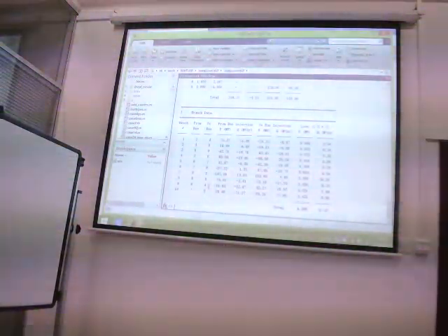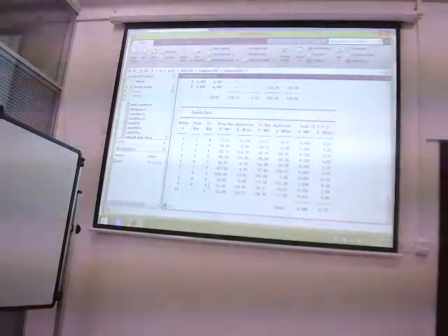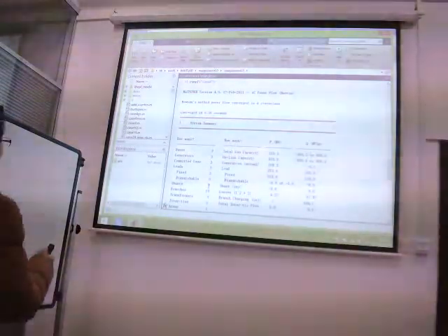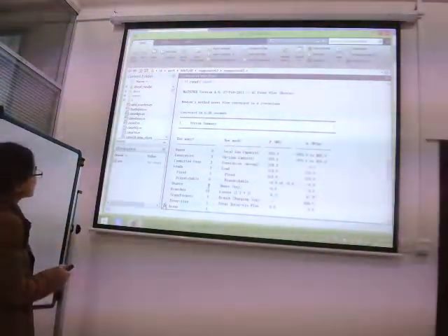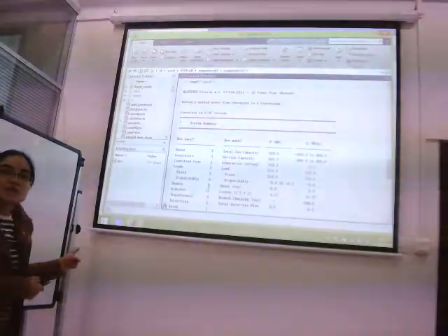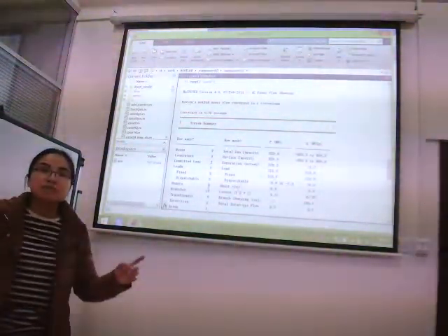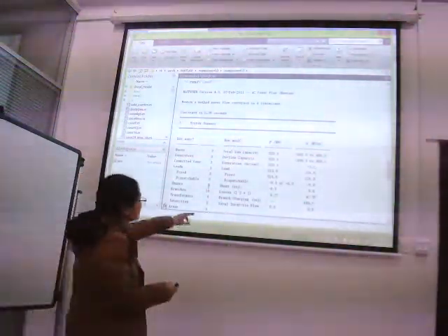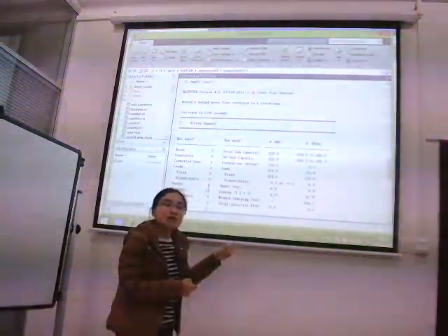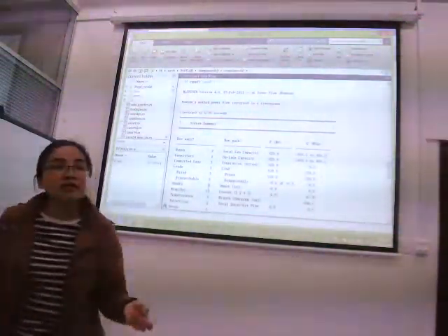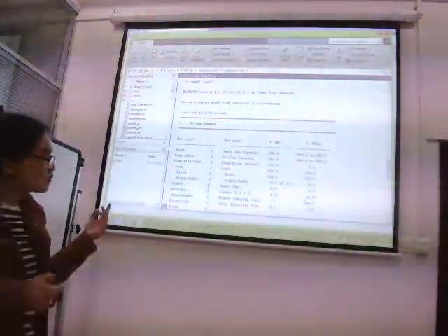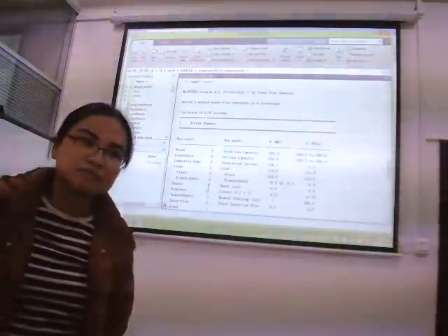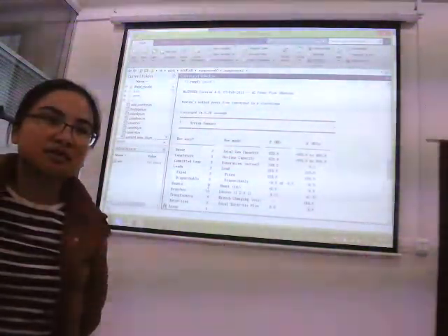Here we have a different value of the power losses. Now let's have a look at this. For task B, the system is more or less the same. We also have 9 buses and 3 generators, but we have 10 branches because we added one branch between bus 7 and bus 5. We can find the results here. The power losses become smaller. It's cheaper and more efficient for the system operator. Why? I asked you to analyze the reason why. Have you considered this, for extra branches?